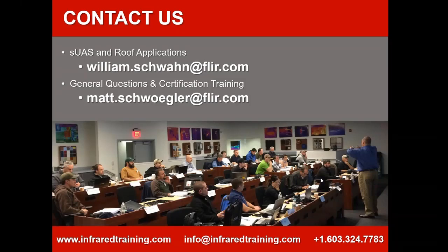Jeff was asking about solar loading. And the definition of solar loading, Jeff, is just basically the sun charging a surface, heating up a surface, whether it's a roof, a wall. Solar loading, solar gain. That's energy, BTUs of heat that are causing the roof surface to heat up. That heat transfers into the insulation. Where there's wet insulation, it takes on more heat. Where there's dry insulation, it takes on less. And so the wet insulation stays warmer longer in the evening after sunset. And so that solar loading is what makes that roof inspection possible.